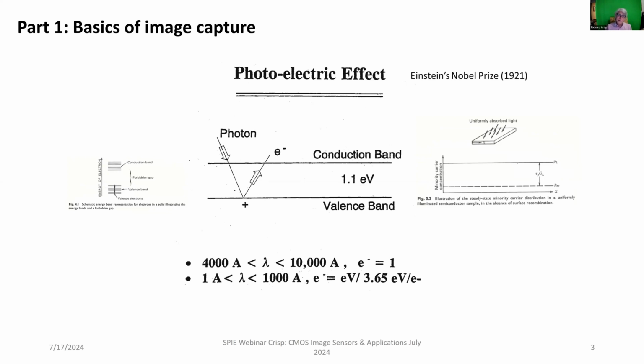So we're going to convert photons into charge carriers in a semiconductor substrate. But then we need to confine them to regions that we'll think of as pixels. And then we need to find a way to manipulate them and move them around so that we can measure how many there are. When we're exposing light to the semiconductor, the wavelength of the light will determine just how many charge carriers we end up liberating per photon. Within the visible light region, we get essentially 1 electron for every interacting photon. So that is a nice convenient number.